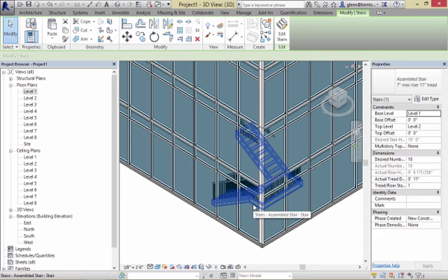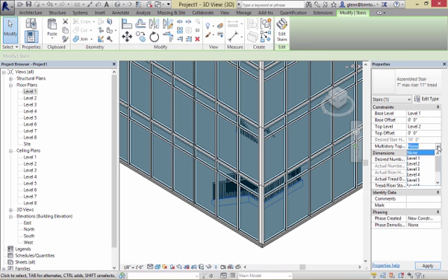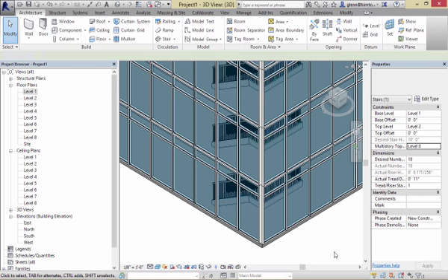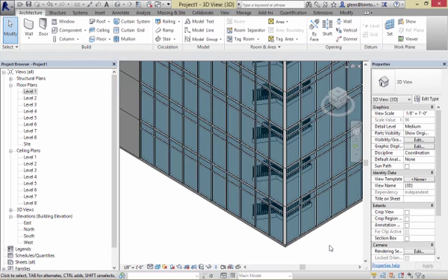And you'll notice that there's not only level 1 to level 2, there's actually this thing they haven't talked about, which is the multi-story top. And what that's all about, if you go pulling down there, is if you have a repeated stair that's going to keep on going and repeat the same pattern, I can actually choose a higher level, and it'll just keep on looping it around until it gets up to that level. So I'll say apply. And it'll make that whole stair going all the way up.